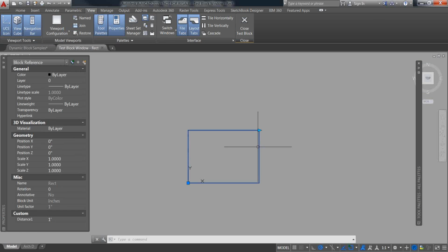So I click test block again. Now when I select it and grab my stretch, it's kind of hard to see on your view, I think. Well, it looks like it's right. So now you see those little hash marks indicating the various sizes. So it's maxing out at, there it is, at 2 feet. Come on, there we go. So it won't let me go past 2 feet, and as I move it, you see it's incrementing exactly to 1 inch, or did I say 2 inch? 2 inch increments here.